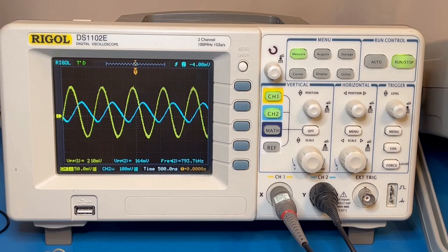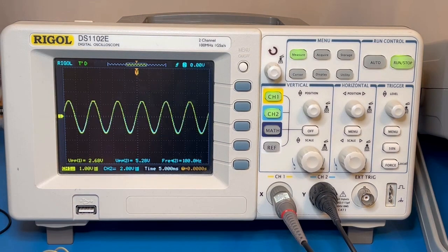The point at which phase shifts become significant and gain starts to reduce is dependent upon the gain setting resistors as well as the chip itself. So this is not a general bandwidth assessment for the LM324, but it gives you an idea of what it's like with a gain of 2. And of course we will be talking about bandwidth considerations, including how to calculate bandwidth for a given op-amp circuit, in later videos.